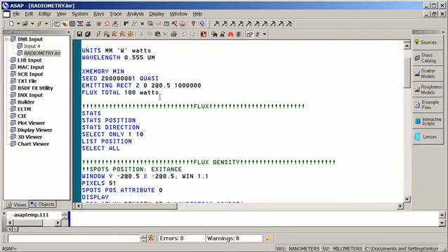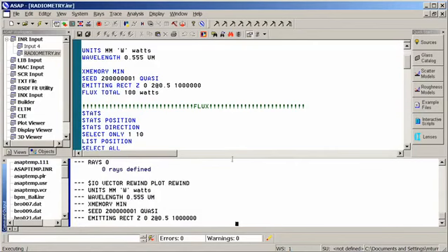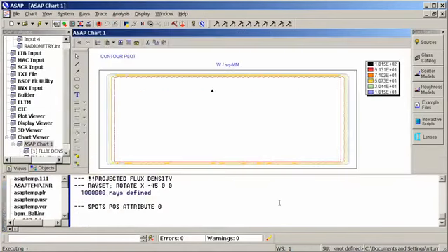So we have just a rectangular source, 0.5 millimeter across, so 1 millimeter square, and from it we're going to launch 1 million rays and look at some spots and directional information about the source. And we'll let ASAP complete the calculation, and then we'll look at some of the information that we've got available.